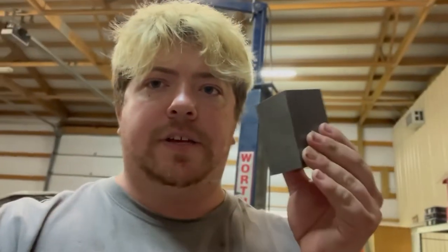Alright, so excuse the mess and the extra noise, but I got my stock right here. It's a 2x2x3 steel, 1-1/8 mild steel. What we're going to be doing is setting up a vise and then basically indicating it in, making sure it's even with the spindle, and then we're going to be setting our G54 WCS with Haimer.